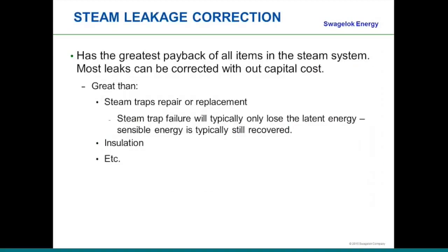The greatest payback of all items in the steam system is steam leakage correction. And we talk about doing this or doing that in the steam system to optimize or improve the steam system thermal cycle efficiency. One of the biggest and greatest paybacks is steam leakage, greater than steam trap repair or replacement.